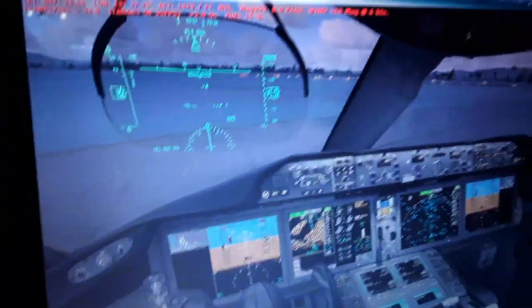The flight management computer input, so we input all the data of this aircraft for this flight. The takeoff gross weight, that includes the empty weight plus the passengers plus the cargo plus the fuel on board, where the fuel is stored in the left and the right wing and in the center tank. So I'm gonna show you.